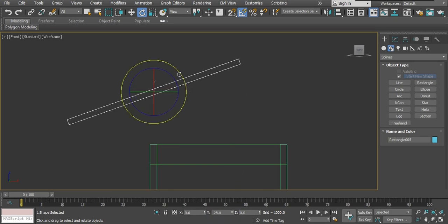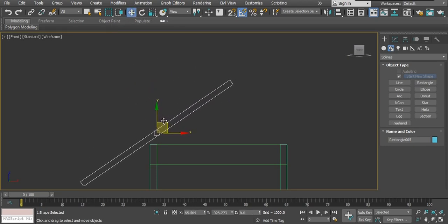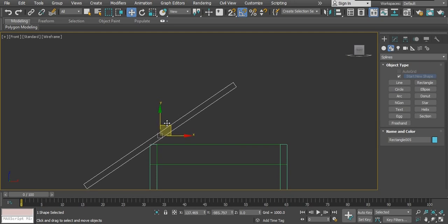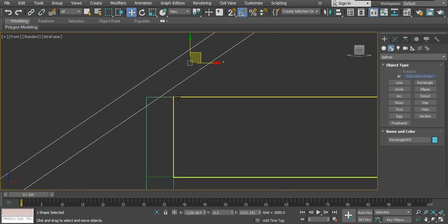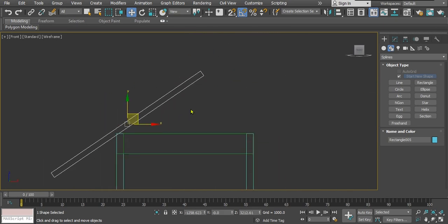So I rotate up until 35 degrees, negative 35 there. Okay, then release. Then move your rafter to roughly where you want it to be, which is somewhere around here. Okay, overlap the rafters a bit, and then make sure that the top of the rafters exceeds halfway of your beam here.